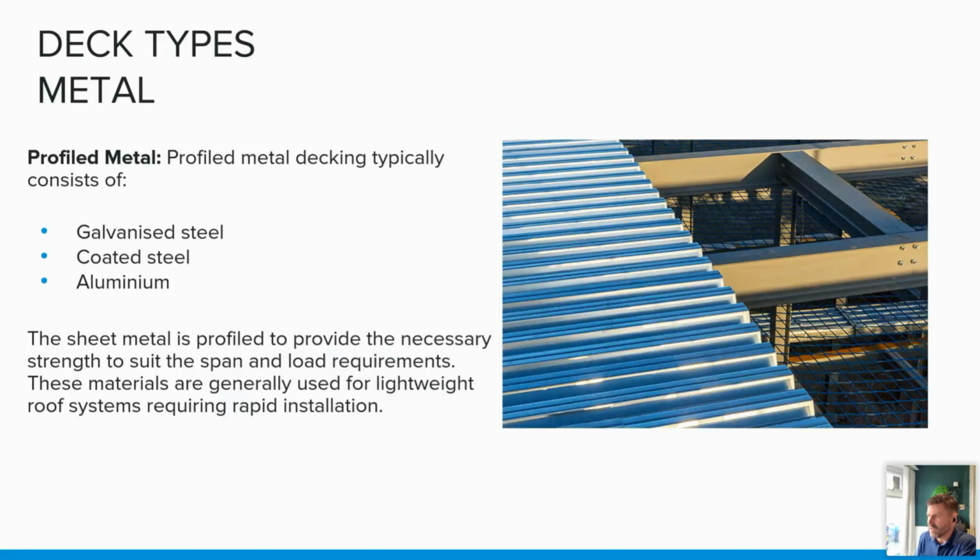And when we're taking a core sample from the top through the single ply, through the insulation, you'll usually see a visqueen type vapor control layer used on these roofs. There are others as well. You can bond to these roofs. The VCL can be bonded to these decks as well. But the deck needs to be specified so that you get at least a minimum 45% bond to the areas, so the troughs and the crowns need to be correctly specified.